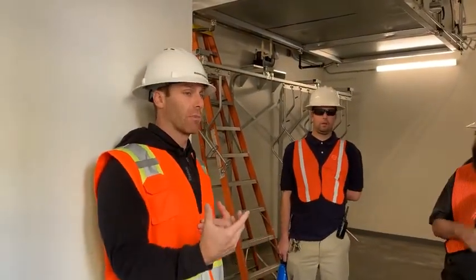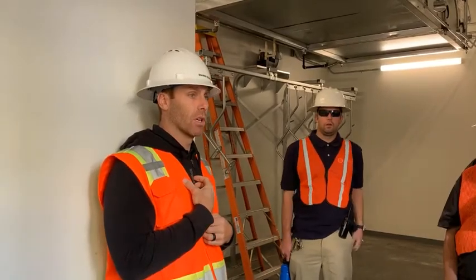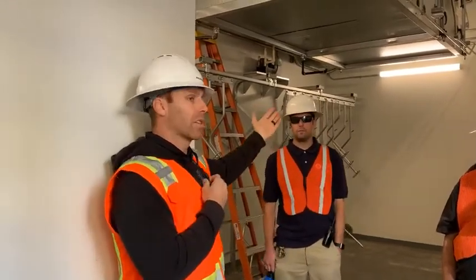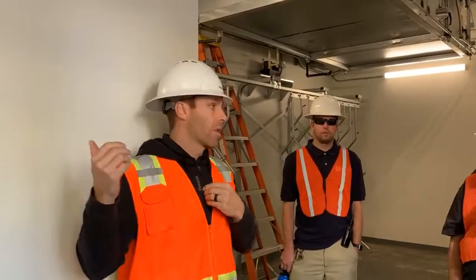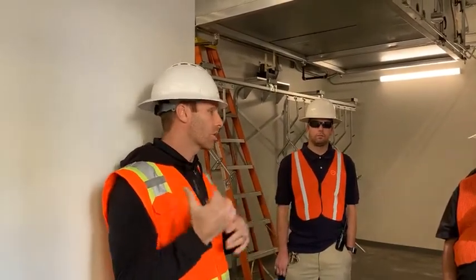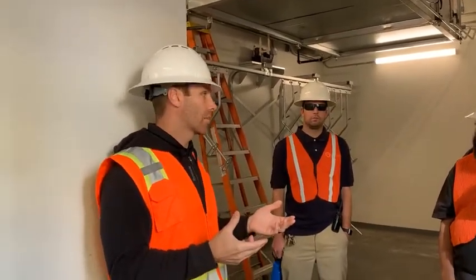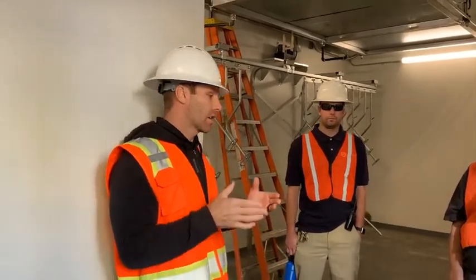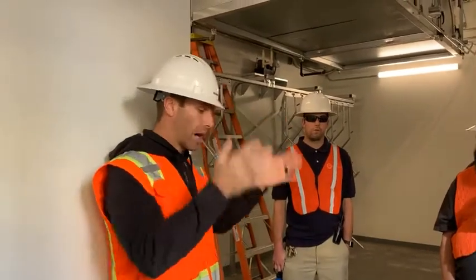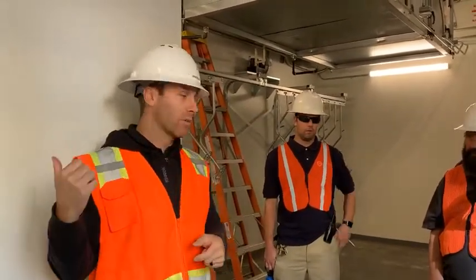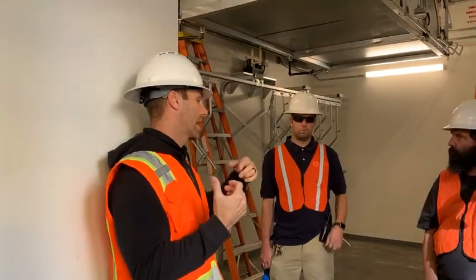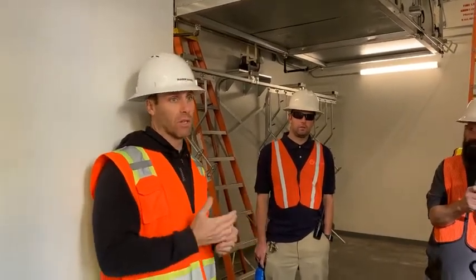Now, from a facility standpoint, if I were to come out here and troubleshoot, and I'm on the other side of the building, I don't know exactly what's wrong, usually I'll plug into that zone. So through a laptop, we have what's called an NCOM kit. I can plug into any zone, okay? Basically, now I'm plugged into that zone, I'm in that room, I can troubleshoot that room from in there. If I'm over here, I can't see what's wrong, I can't see what's happening, I can't see exactly what devices are doing what, but being over there, it's going to be much easier for me to troubleshoot that way.